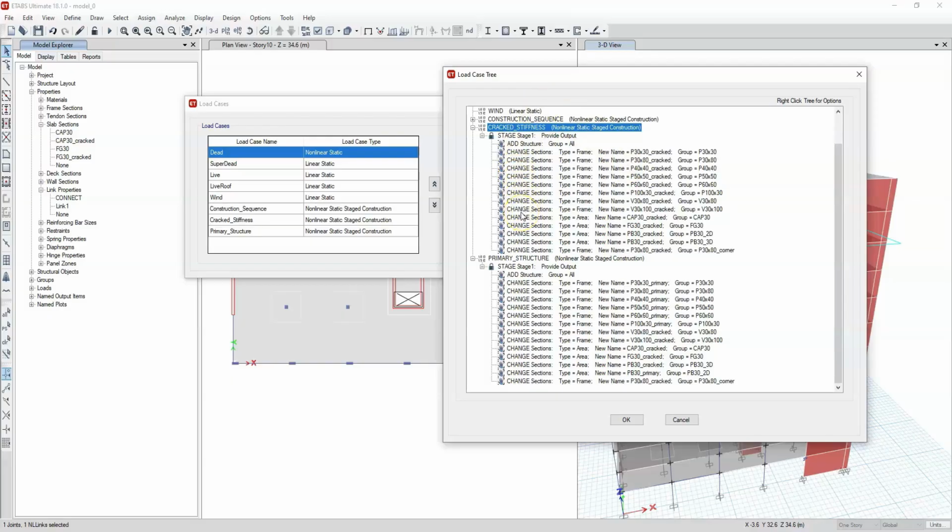This model serves to classify the structure, to check secondary elements, for example, punching shear, and, very importantly, to check the contribution of the secondary elements to see if we made a correct and possible definition between primary and secondary elements. In this structural phase, we have different section modifiers. That is what makes the difference in being able to apply the 50%.